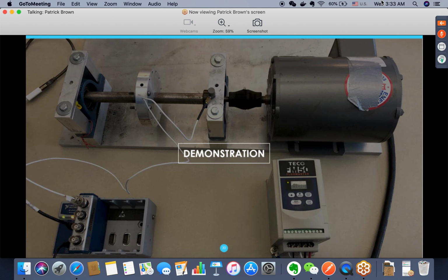And now I'm going to get into a demonstration using our Predictronics DAC software suite of this test bench, a picture of which is shown on my screen. It's basically just a motor with a rotating unbalance and a single accelerometer connected to an NI data acquisition device. As the motor turns, the unbalance mounted on the flywheel moves around, creating a vibration that the accelerometer can then pick up and transfer into a voltage signal. It goes into the NI module, which then feeds the data directly to our PC, so we can log this data.